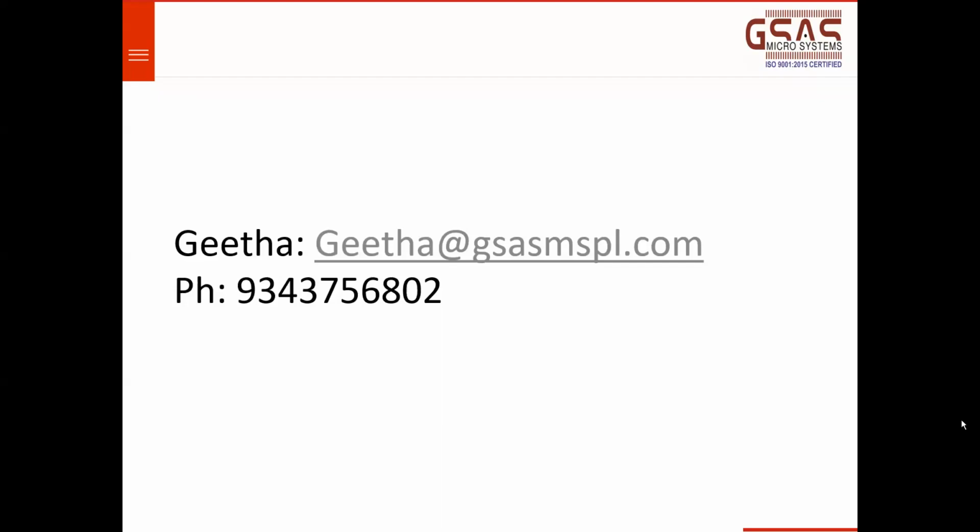What was not showing on your PC? Hello, I'm Christine. I think the simulator feature was not showing in the Keil which I have. I have the light version only. What version are you using, Christina? On that you have to install the legacy pack, because in MicroVision 5, simulation support for many devices is not provided. To simulate the device you are planning to use, you have to first check whether the device is simulated. If it is simulated, then download the legacy pack.